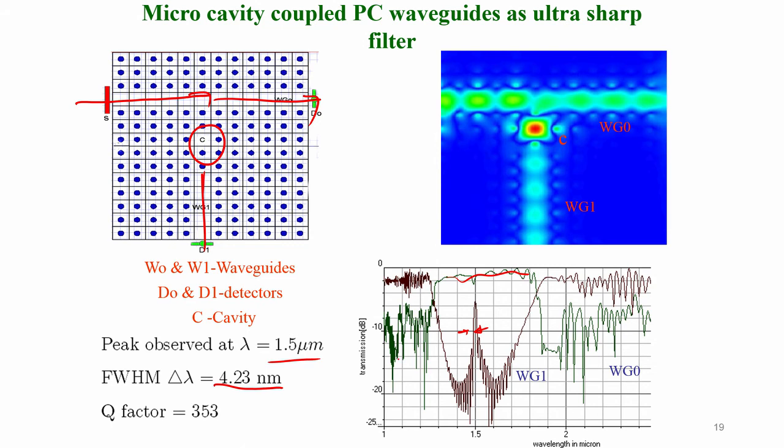But of course, as you note there is an important limitation that the Q factors of the resonance are quite small. So, in most of the engineering applications including optical applications, you need Q factors of the order of several thousands. So, that is an important challenge for the designer of photonic bandgap structure based devices.